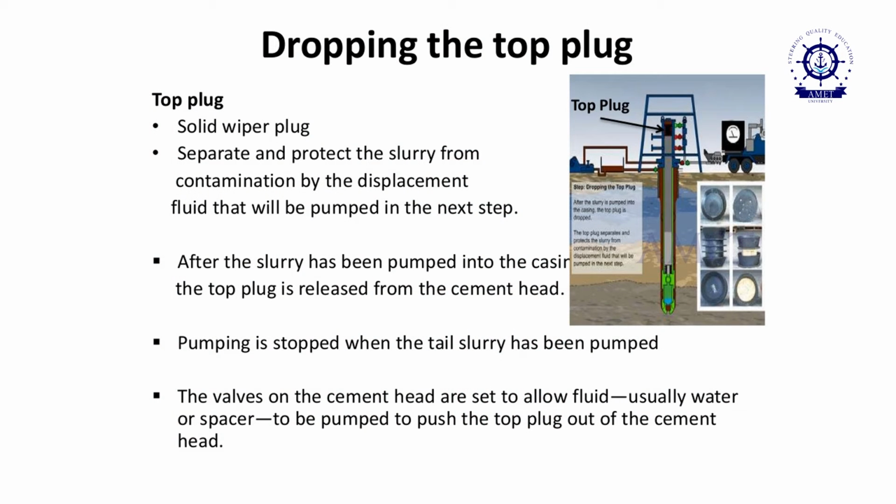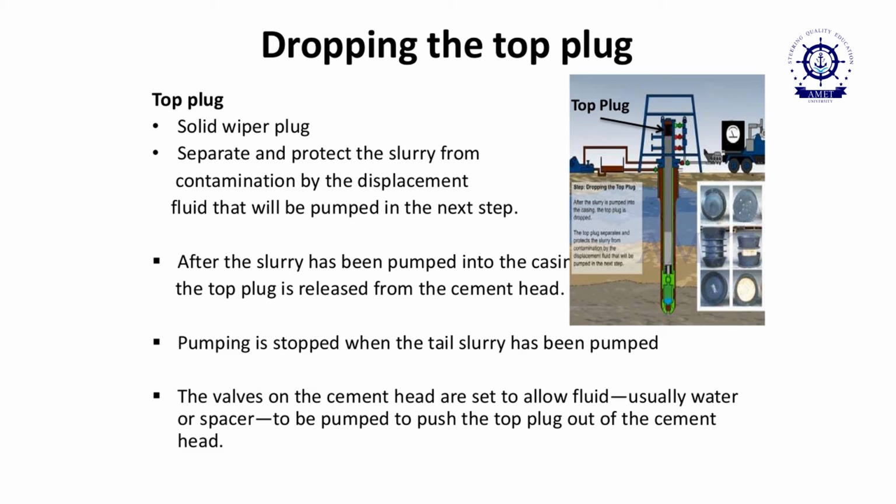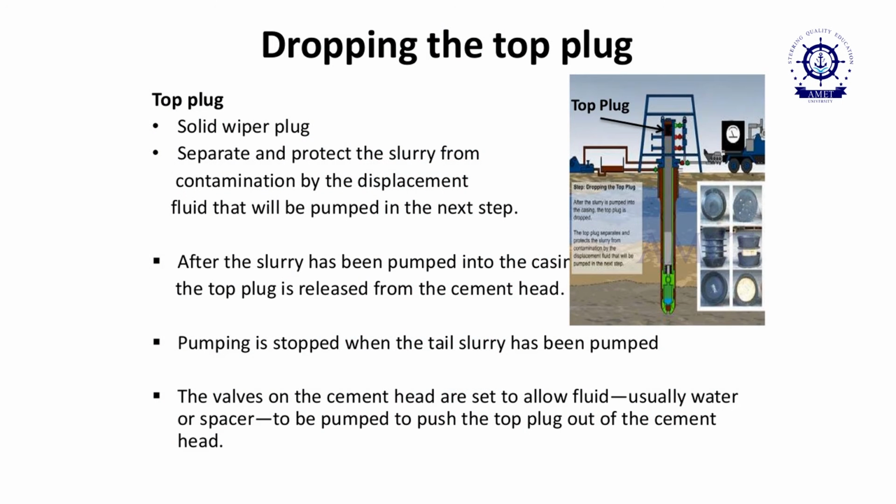The cement slurry only can be pumped into the well bore to seal your annular space. We cannot put more than that, because if we use excessive cement, it will spoil our economy. For that purpose, once we have prepared the cement slurry, it will still be existing only inside your pipe, because some of the slurry cannot completely go to the annular space. So I have to push everything to the side of your well bore, then I have to directly use some spacer, it may be like displacing fluid.